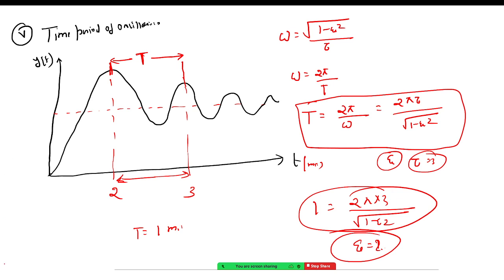Now what happens over here? You see this is the ultimate value of response. Sometimes the response is fluctuating over here. What happens here is that it will come under a particular range and start decreasing. Here this is 5%, here this is minus 5%, let's say. From this particular time, the response reaches 5% or minus 5% of its ultimate value, right? This is called the settling time.